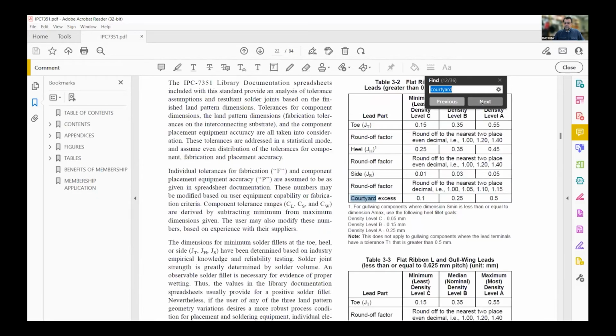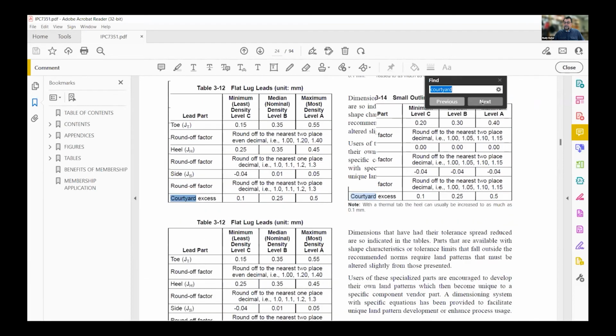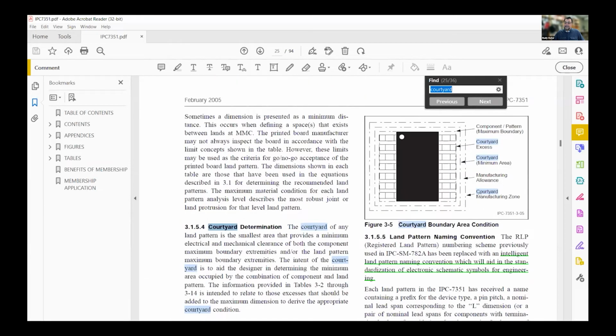There we are. That's the graphic I was looking for. So you can see here when you choose your levels, you can choose how closely you want to pack your components in by choosing most, normal, or least amount when you're doing your IPC package generation.